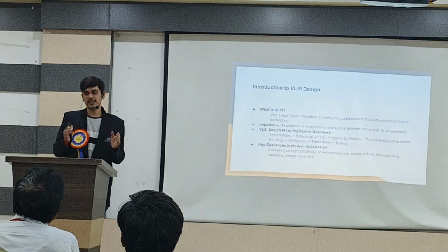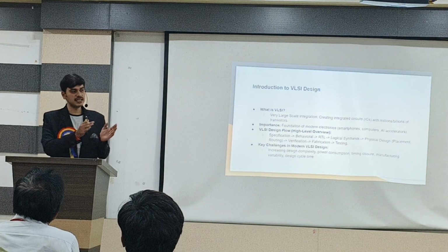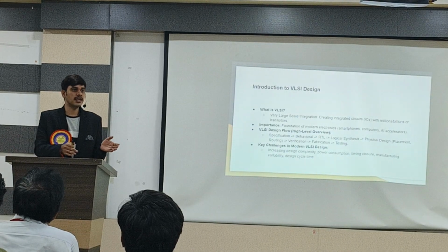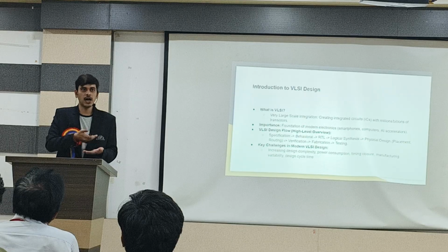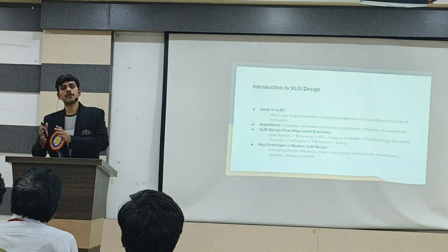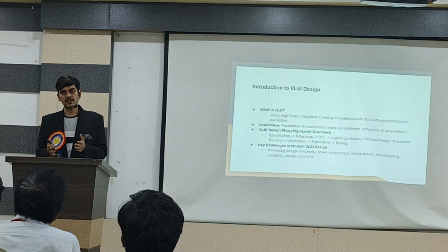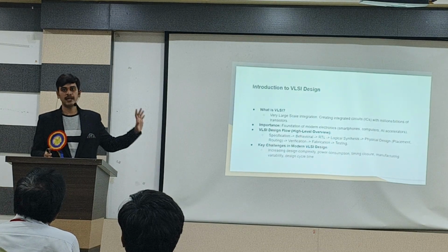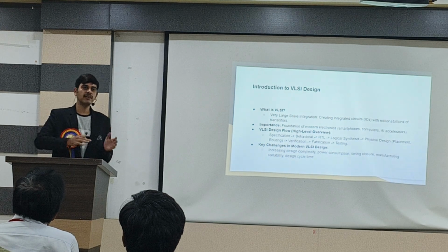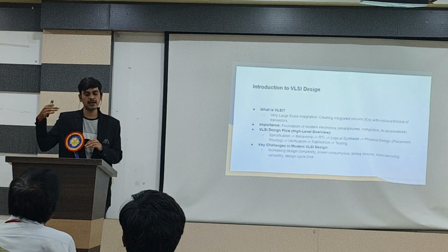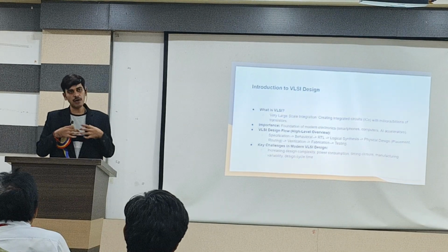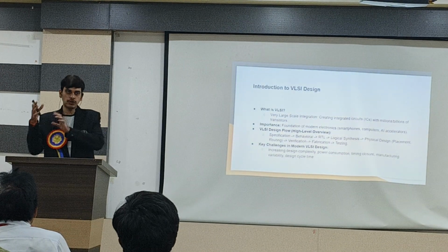But finally, the chip is hardware, which has to be transferred into a layout. Whatever you do in coding has to end up on a chip, on hardware. So this code we have to convert into a layout. That's the total process. The end of it is called tape-out. That's the last stage, where we deliver the GDS to the fabrication unit, and then we get the chip fabricated. Whatever designs we have done will be fabricated onto the chip.